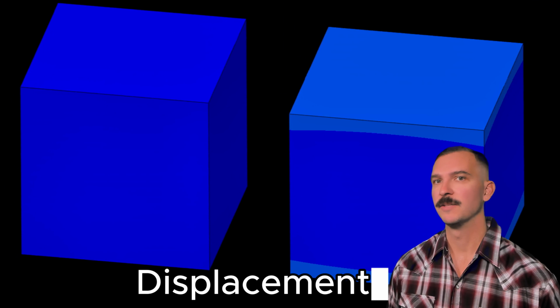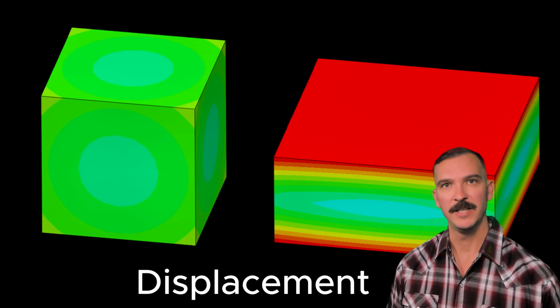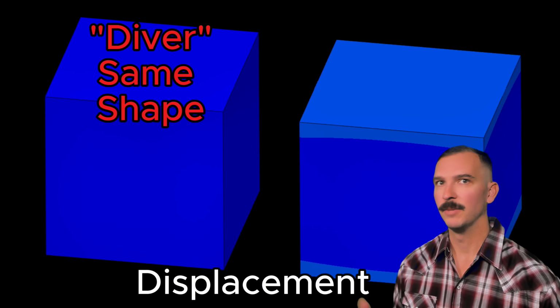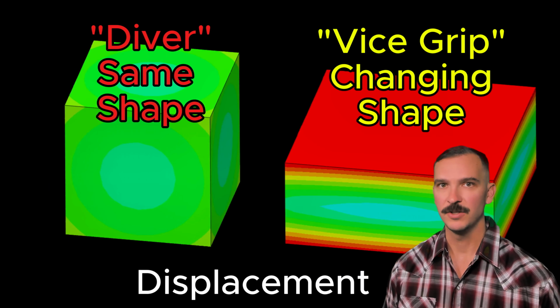First, look at displacement. Both blocks are moving. The hydrostatic block on the left is shrinking. It's changing volume. Materials generally don't mind this. But the block on the right, it is bulging out at the sides. It's changing shape. It's distorting.